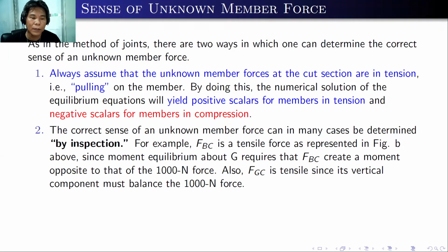The second method is that the correct sense of the unknown member force can in many cases be determined by inspection. Again, I want to emphasize this one. You need to develop that skill by inspection, so that you will be able to determine directly what particular force a member of the truss is carrying.